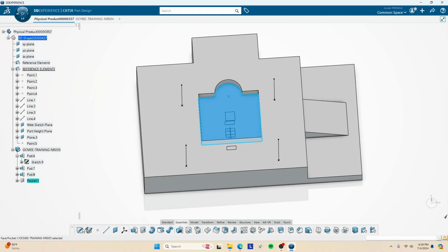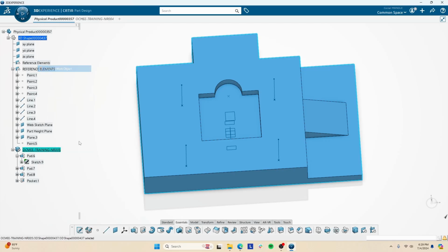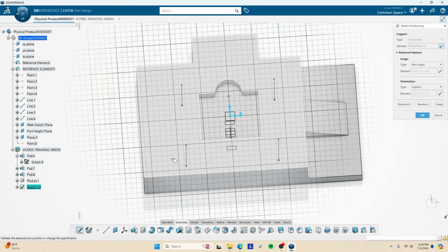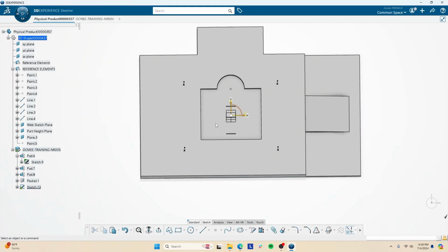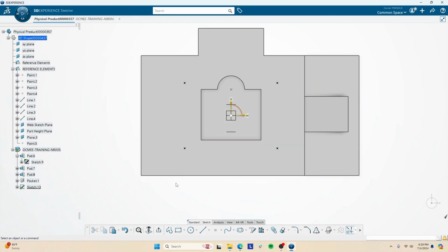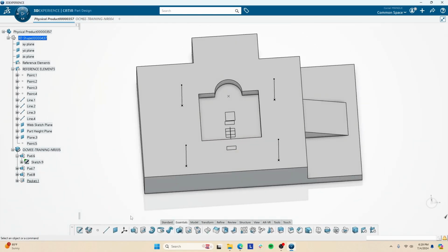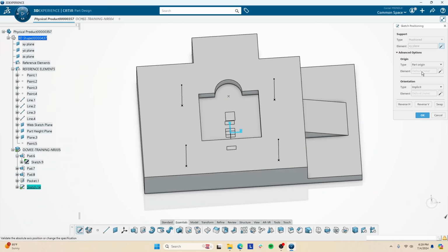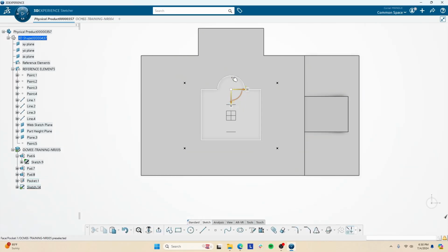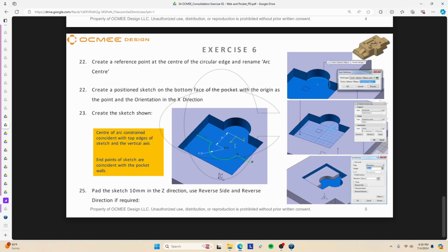So we click this. I almost made a mistake. Define in-work object to be your main body again. And actually, before I do that, I should exit. And without clicking anything, I'll click this first and have a projection point to be my origin. We'll click that reference point that we just made and project it onto this face. And just for the sake of following the tutorial slides, I'll switch around the axis. Seems like it's 35 away with the same radius.